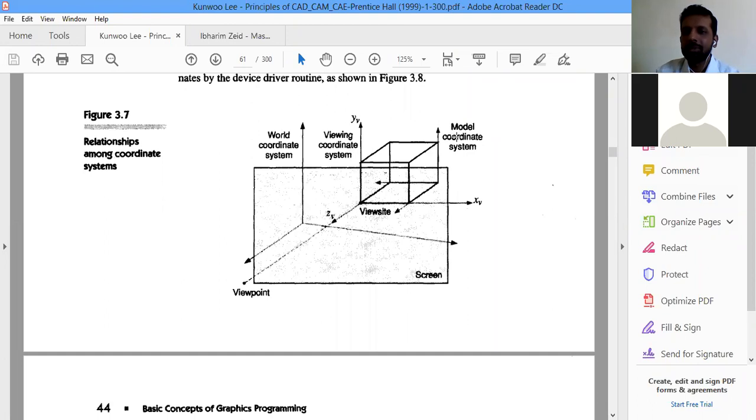And the same thing is also depicted in SolidWorks and in other modeling softwares as the working coordinate system, WCS, right? So that is nothing but the model coordinate system also. Even in our ANSYS or Abaqus also, especially in ANSYS, we will use one option to enter the coordinates. We'll go to an option called active CS, that is the active coordinate system, nothing but the model coordinate system, where we'll define what the x value, y value, and z values are, right? And whatever that we are going to enter.